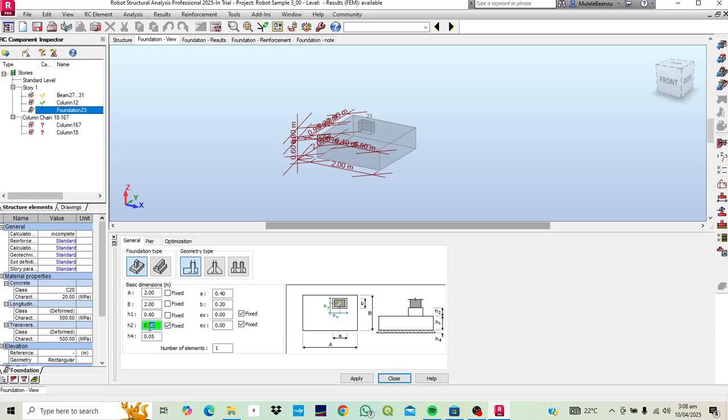Here the software will give you a warning if you use 1.1, but I like using that because it more accurately depicts the height of the stub column, which is usually 1.1 meters below the slab level. And H1, this is the depth of your footing. You can see H1 here. This one you can assign it as, I like to use 0.4, and I like to fix it.